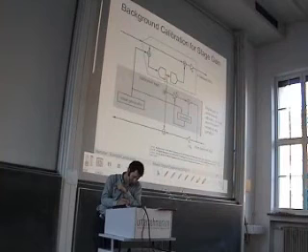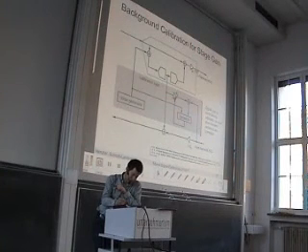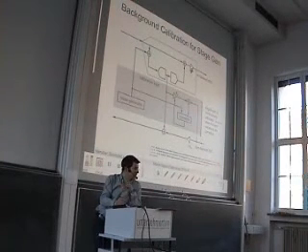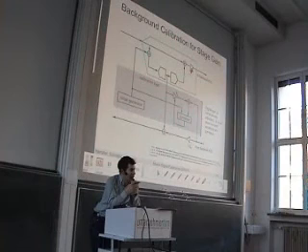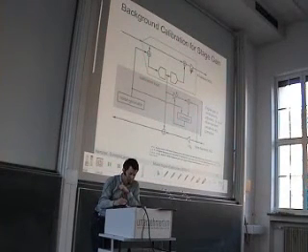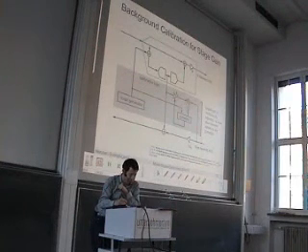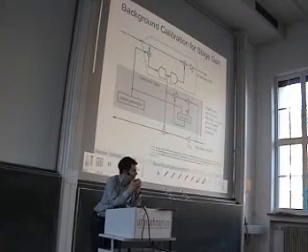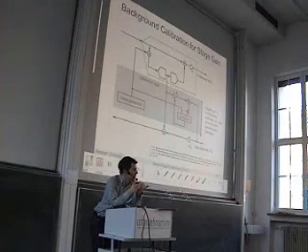So we have the direct signal scaled by AD, we have the signal through the backend ADC scaled by a factor of A, and if A and AD match, then the difference of these two signals should be 0. If they do not match, then we have to adjust the A digital until they do match.